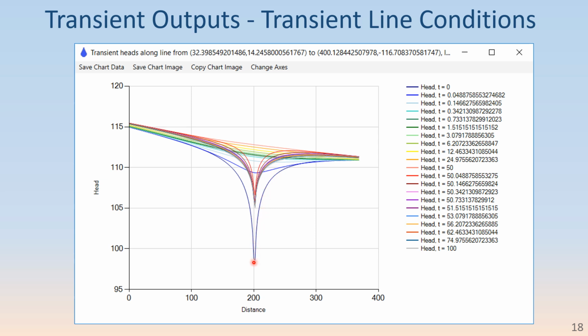In the first period of the transient model, that well was shut off, and you get these curves, from the lighter blue up through the greens and the yellows and into the reds, up to time 50. It looks like the water table, or head, recovered to get rid of the cone of depression, for the most part.